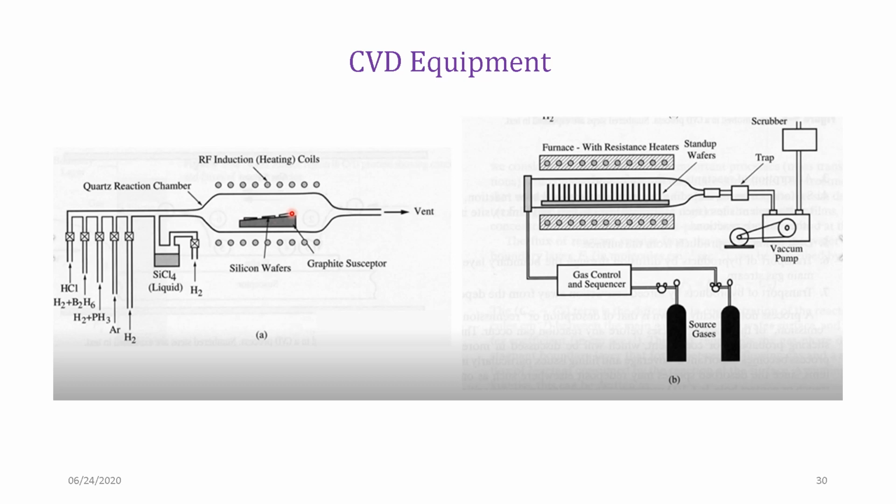Coming to chemical vapor deposition. You have the CVD equipment described here. You have different lines of gases that go through. You have a precursor, sometimes it's solid, sometimes it's liquid. And then you have a chamber, which is a kind of furnace or heater. You have a small substrate holder. And then you have a vent valve.